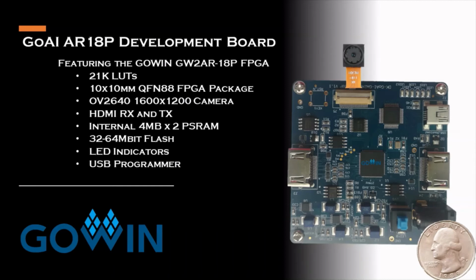This board has HDMI RX and TX, and there's enough room to have that, and we use that in a lot of the demos. So this is kind of nice to have HDMI RX and TX because you can use an HDMI input stream during your development for video inference applications. And then also you can output the video. We have a text overlay, bounding box type capabilities within the design, and you can add those to your HDMI output.